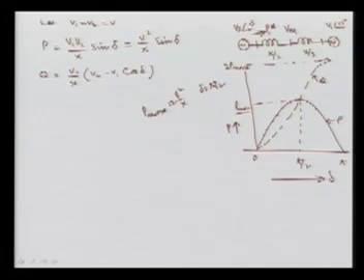For the reactive power, in this expression you can again put V1 and V2 equal in magnitude. Then the curve for Q here will be this dashed line. At delta equal to pi we get 2 P max.